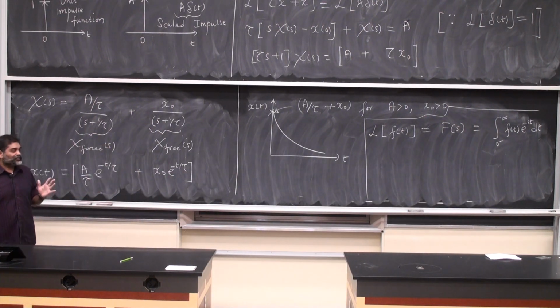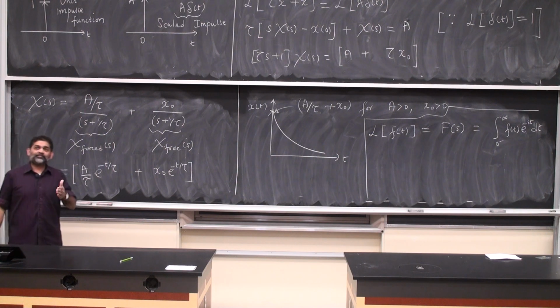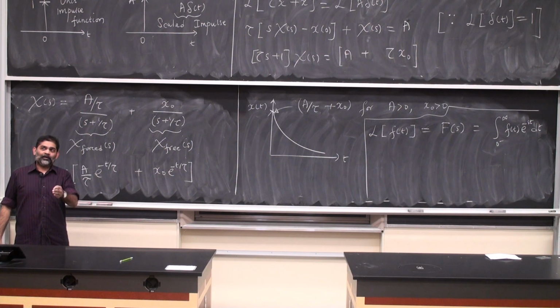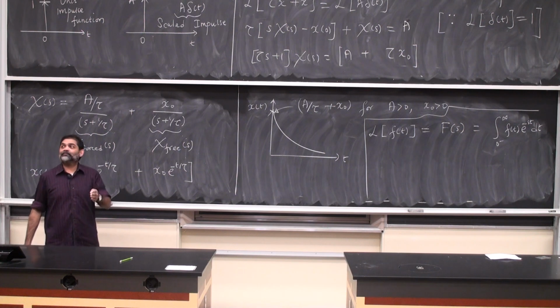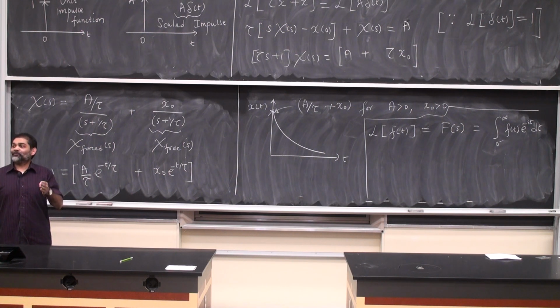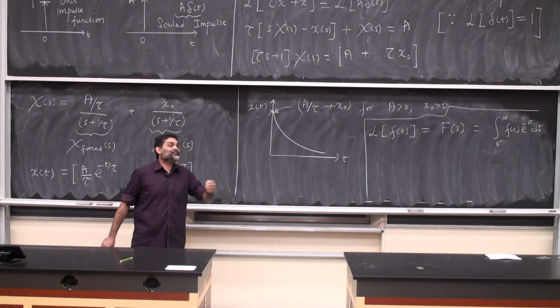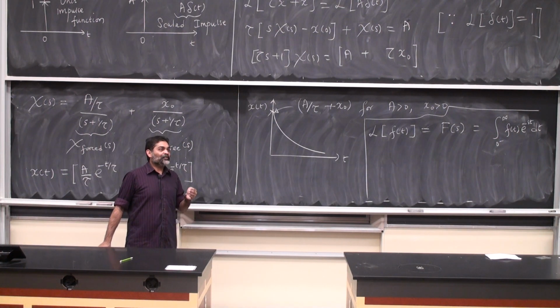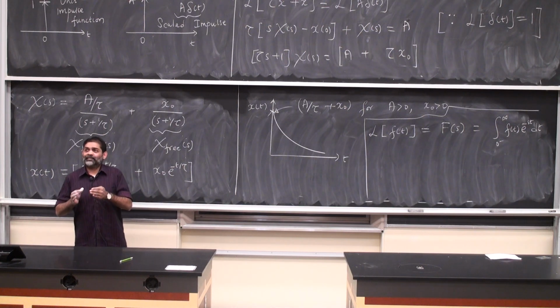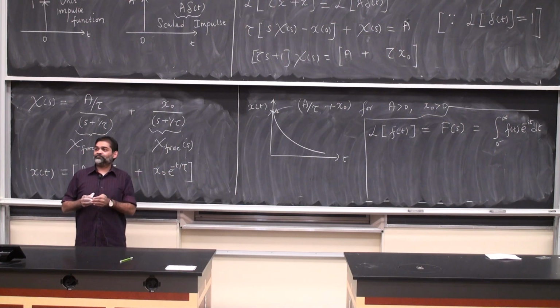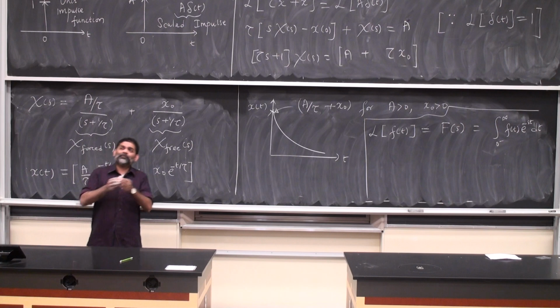in many situations, I will start the clock, I will wait for some time, and when the system is not seeing, I will come and give it a good kick. Which means that my forcing function is actually not starting at 0, but it's starting a little after 0. Such forcing functions are called time-delayed forcing functions. I don't apply it directly, but I apply it a little later.